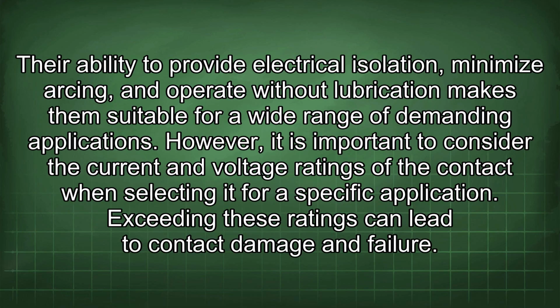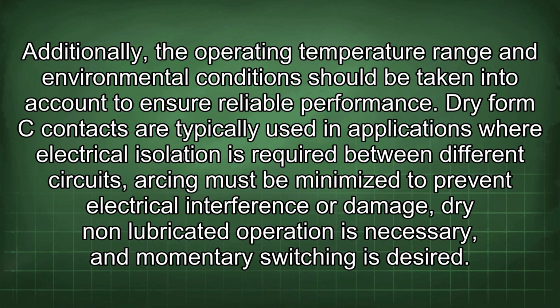Their ability to provide electrical isolation, minimize arcing, and operate without lubrication makes them suitable for a wide range of demanding applications. However, it is important to consider the current and voltage ratings of the contact when selecting it for a specific application. Exceeding these ratings can lead to contact damage and failure. Additionally, the operating temperature range and environmental conditions should be taken into account to ensure reliable performance.